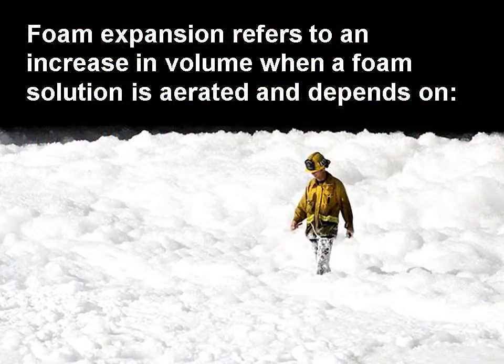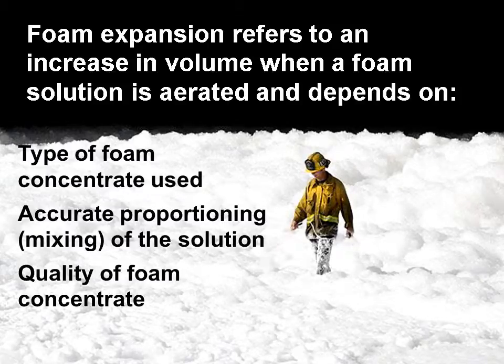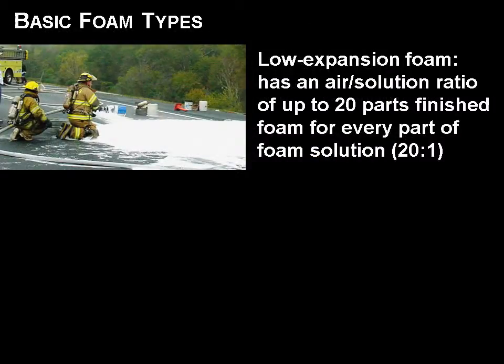Foam expansion refers to an increase in volume when a foam solution is aerated and depends on the type of concentrate used, accurate proportioning, mixing of the solution, the quality of foam concentration, and the aspiration method.